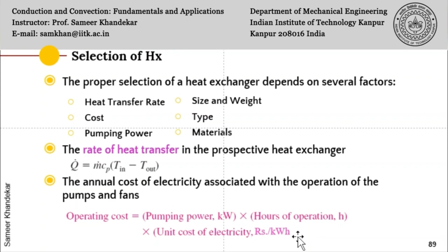So you have to find out the long-term operating cost, you have to find out the long-term maintenance cost, you have to also see whether there is enough space available for maintenance where the heat exchanger will be installed, because you have to take out the end channels, you have to remove the shell tube side sometimes, you have to clean the tubes, you have to put some equipment there. Also you have to check the vibration levels and the foundation, possibility of erecting a foundation at the local level. Also regular maintenance has to be done for the heat exchanger, so personnel has to move inside for not only doing the maintenance but taking regular data, so that the effectiveness and the efficiencies can be calculated. So all these parameters are there which will determine how you select a heat exchanger.